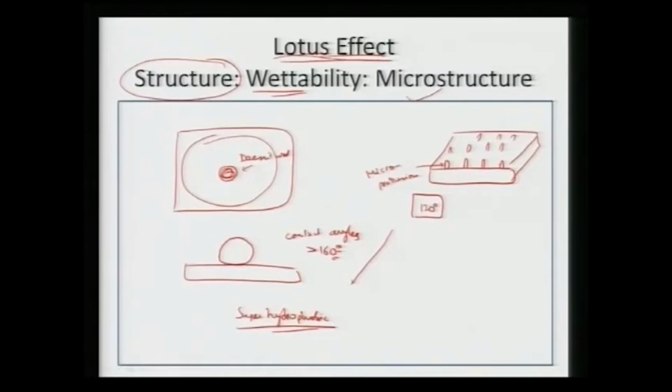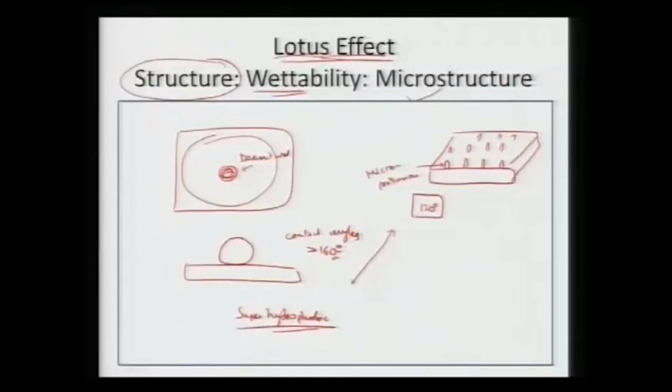So it means that the chemistry of a surface is not enough on its own to govern the non-wetting. There has to be some extra feature which is governing the overall non-wetting to increase the contact angle from 120 to 160 degrees. These micro protrusions are the first regions which enhance the contact angle, and then there are certain nano hairs present on each protrusion. So each protrusion will have nano hairs on the surface, which in turn also increases the roughness by a couple of times.